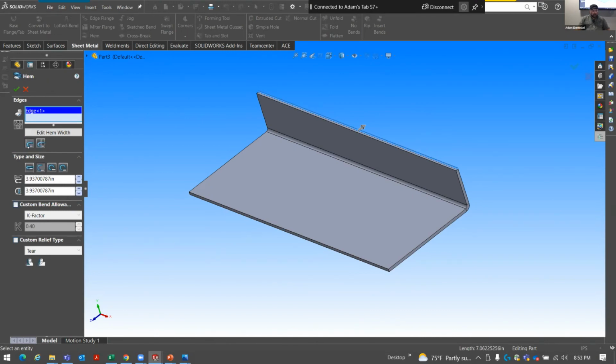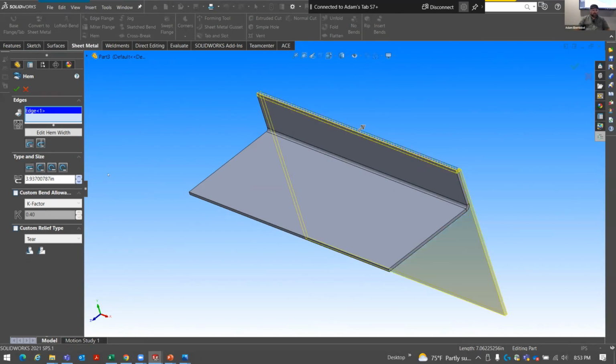You have different options. You can do your material inside, outside, of course, just like before, but you could say you want it to be closed, you want it to have a loop, you can have these teardrop shapes, or you can add it as if it's being put in a roll former, right? So you put it in, it kind of rolls it on top of itself. I think the most standard typical one is probably this one that folds down on itself, because a lot of times what the press brake will do is they'll stick it in, create the bend and bend it over far enough, and then they'll pinch it together. That's probably your most standard and easiest one to create.